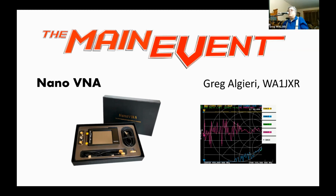Well, the problem is they only give you a cal kit in SMA. So you'd have to get your own cal. Right. If you had a BNC cal kit, then you could put the adapter on and calibrate in BNC. Or you'd have to put two adapters on and go back to SMA. Well, you just leave the SMA connector saver on, and then just put your SMA to BNC adapter on top of that. That's the whole purpose of the connector saver, you're not mucking with the ports on the instrument itself.